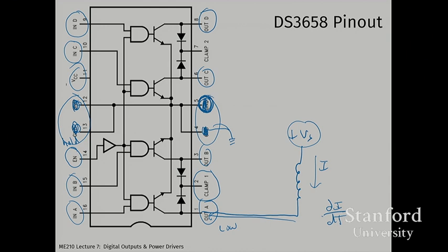And for inductors, that leads to an induced voltage that's proportional to di/dt times the inductance. Particularly when you go from a steady current to no current abruptly, that di/dt is a huge number. That leads to a huge voltage spike on the terminals of the motor. And what you do with this clamp diode system is you make a hard connection from the high side.